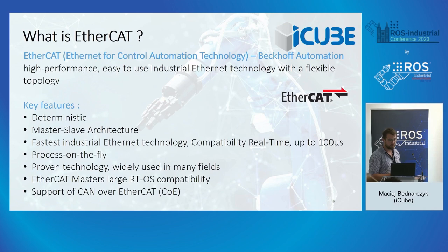It's a very proven technology which is widely used in many fields, in many robotic systems, in many industrial environments, and it has a wide panel of EtherCAT masters, which are in many cases compatible with real-time systems, and it also supports CAN over EtherCAT, which is CoE.